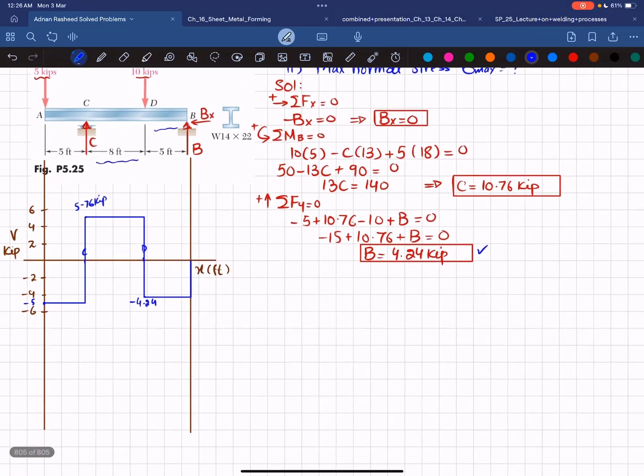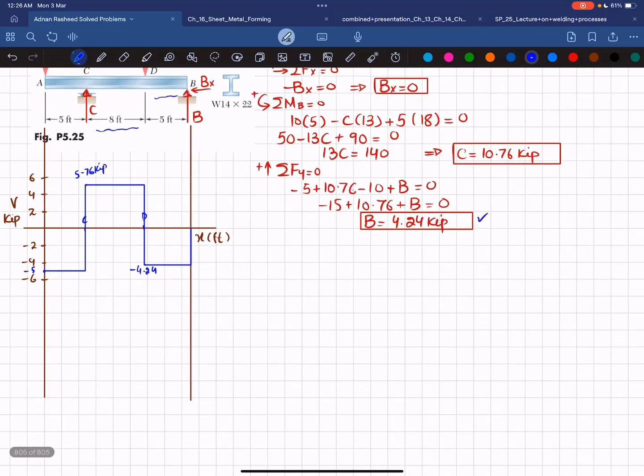Moving toward the bending moment diagram, so again I have to draw a horizontal line to show the length x in feet, and on y-axis you have moment that is having unit kips multiplied by feet. Okay, let's take one division is equal to 10. So this is 10, this is 20, this is 30. You can take as per your own requirements, minus 10, minus 20, and minus 30. Okay. Starting from first point at A, you can see you do not have a moment at x is equal to 0, so bending moment will be 0 at this point.